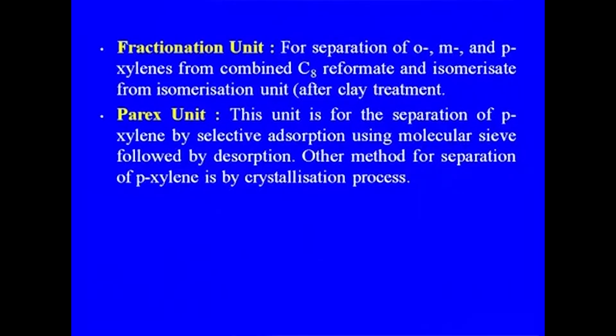Then the fractionation unit for the separation of ortho, meta and paraxylene from the combined C8 reformate, and isomerate from the isomerization unit after the clay treatment. The Parex unit is for the separation of paraxylene by selective adsorption using molecular sieve followed by desorption. This was the real breakthrough, we can say, in the production of paraxylene, the coming of the UOP Parex process. Other processes have also been developed for separation of paraxylene, but it was mainly the role of UOP which developed this process.